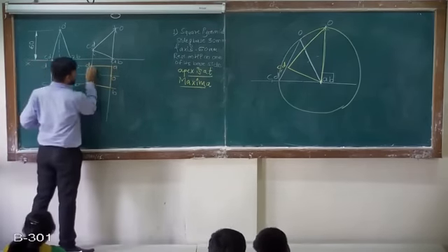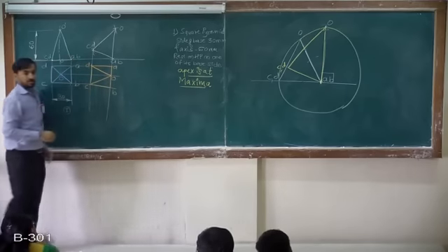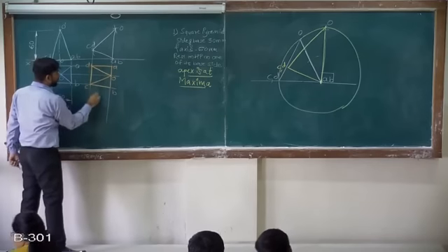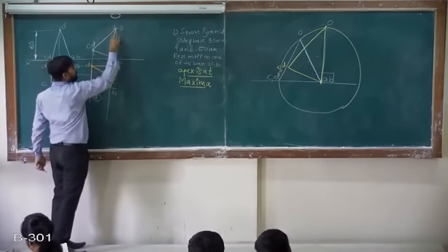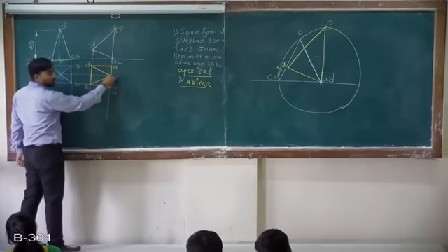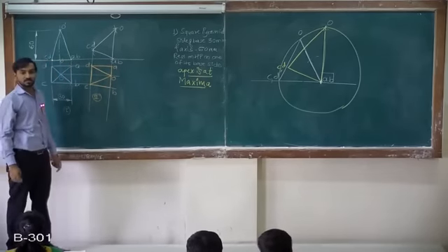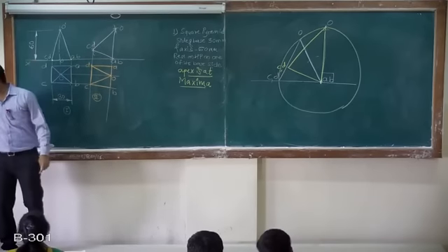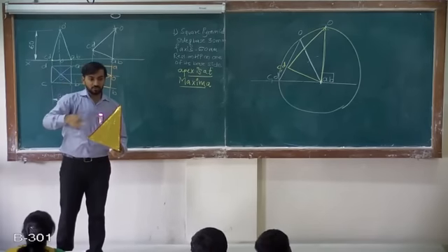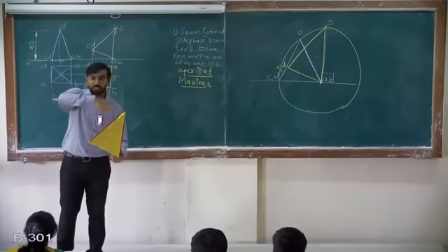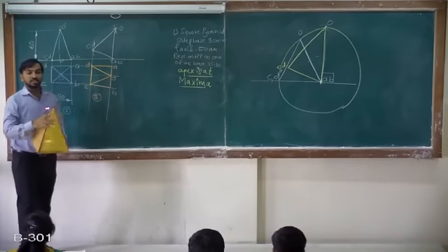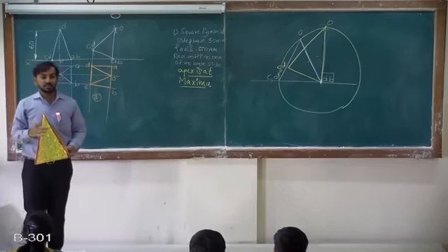And you can see this also, right? So this is second stage stop. As projections of OAB are on the same line, I'll get ABO on this same projection. So this is the case. So you can see these edges in the top view. When it is vertical, you can see these two edges in top view, right? So I have drawn these two edges, continuous thick as visible lines. Got it?